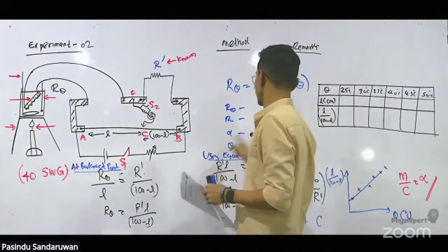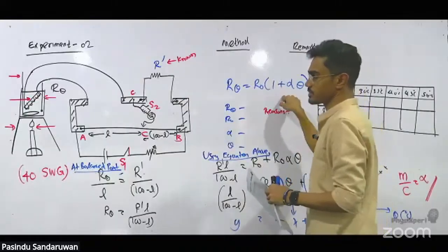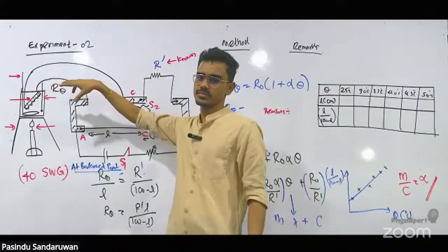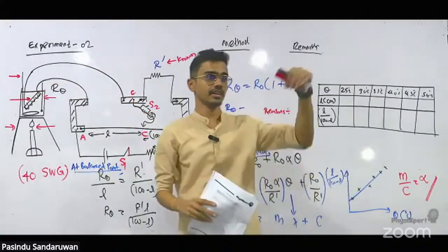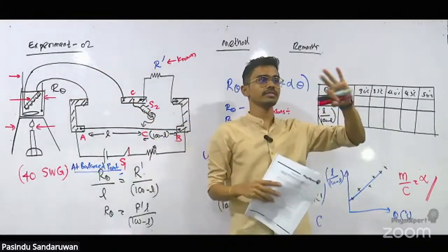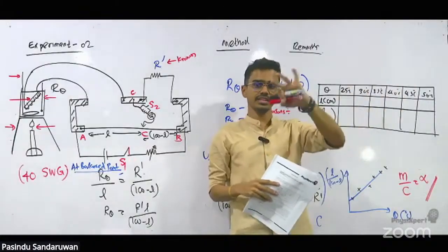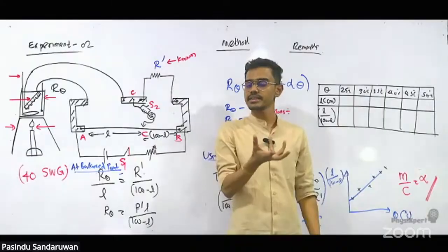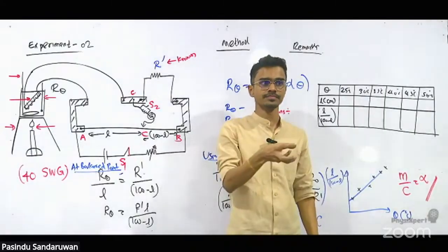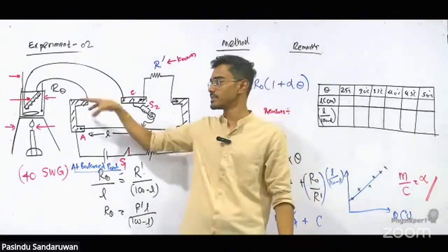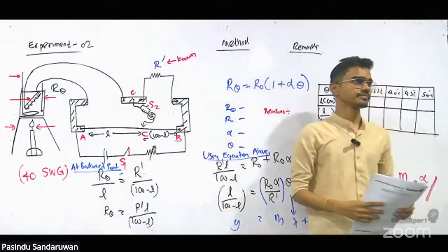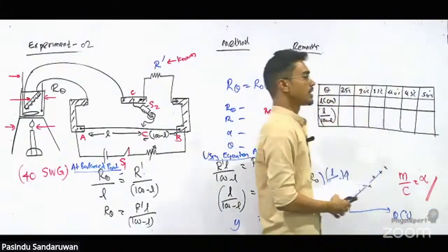So first thing, if such a case happens in the meter bridge, there will not be an issue from the resistances. But when it comes to the potentiometer, we are doing the same practice, checking A to B and A and B. After checking, if that happens, it could be an issue in a secondary circuit. But here you don't have a secondary circuit. So the probable reason is a loose connection.